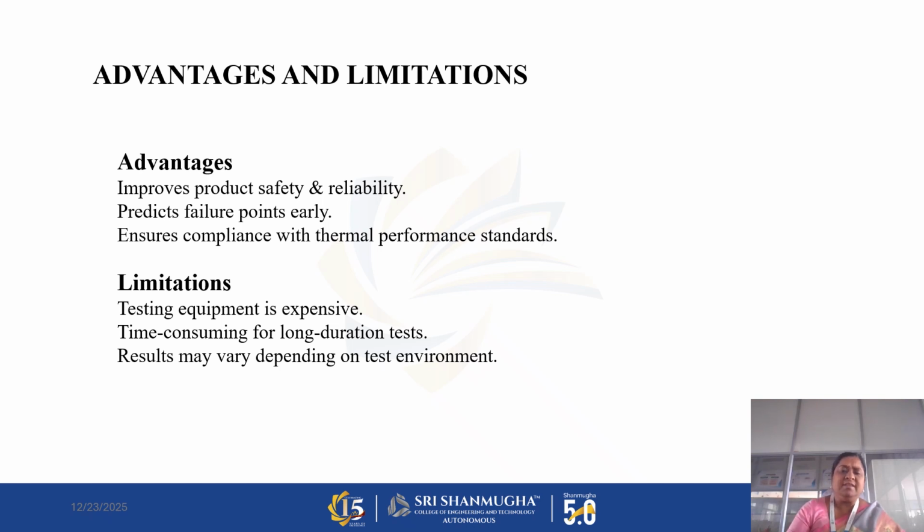So when we test PCBs or some special material, we have to always make sure that the room temperature is maintained constant. Every time we test, suppose one day we are testing at 30 degrees centigrade, the next day also when we check the same PCB, we have to make sure that the room temperature is maintained at 30 degrees centigrade. Otherwise, it will give varied results.